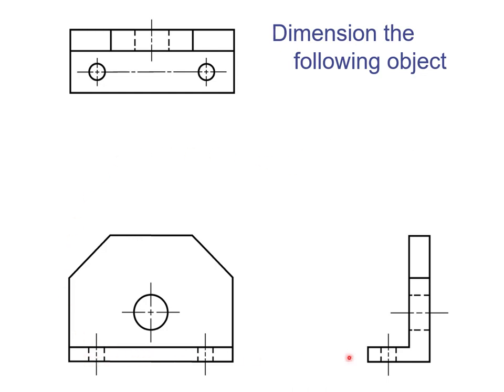So a good datum is the base. This can be one of our datums. We can actually consider the back surface our primary datum because there's more surface area than the base. But maybe it was manufactured with this mating up to the 3-axis table. Okay, so this is a good datum. This is a good datum here.